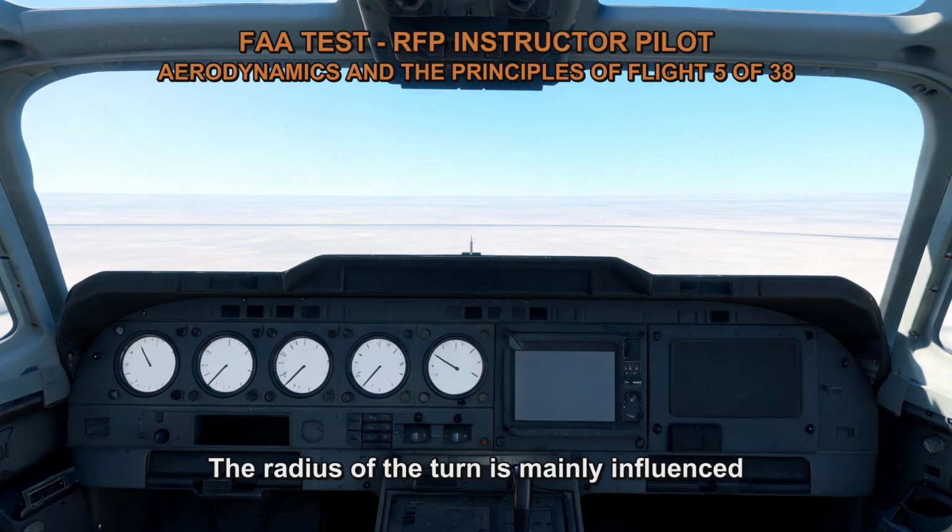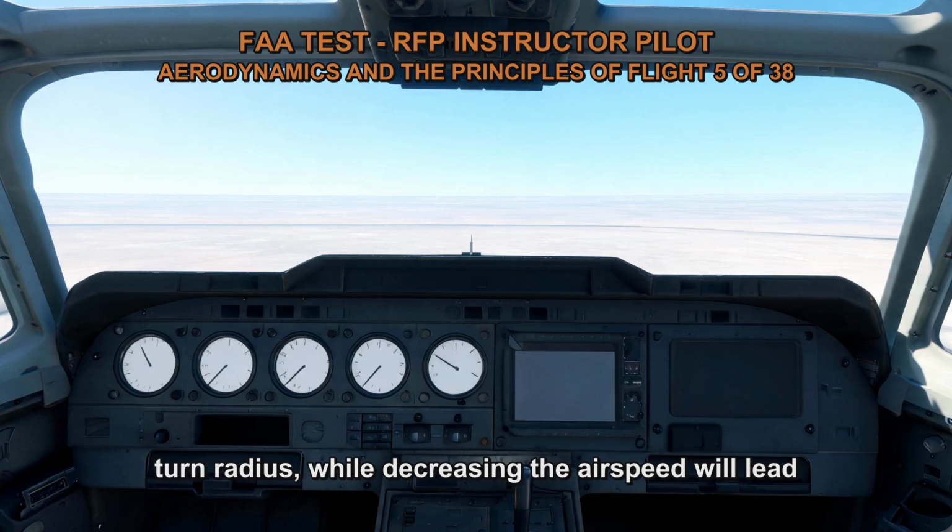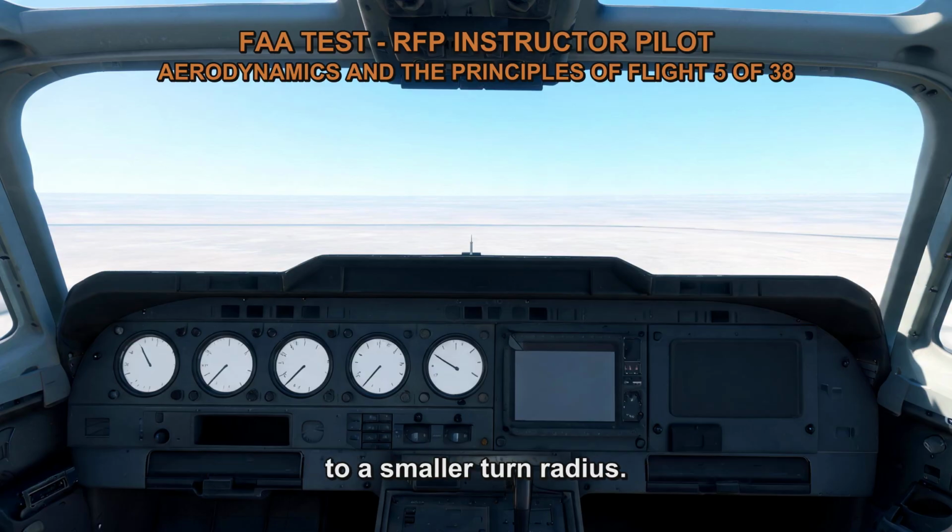The radius of the turn is mainly influenced by the airspeed. Increasing the airspeed will result in a larger turn radius, while decreasing the airspeed will lead to a smaller turn radius. So, to decrease the radius of the turn, we need to decrease the airspeed.